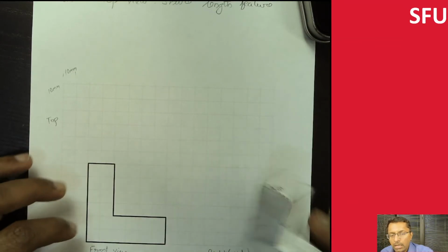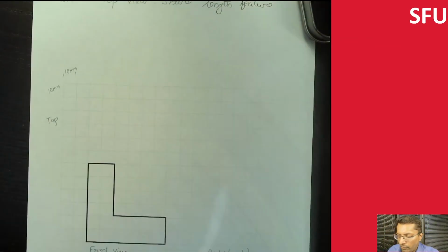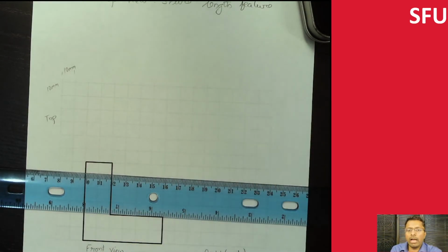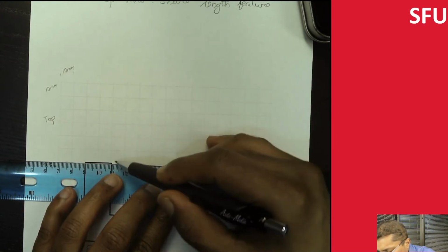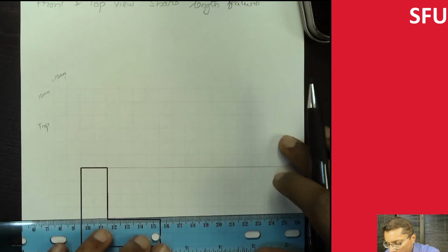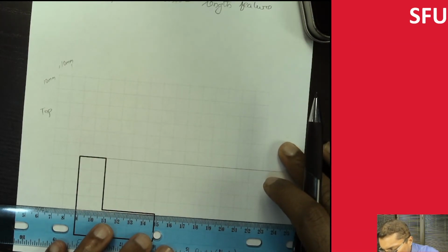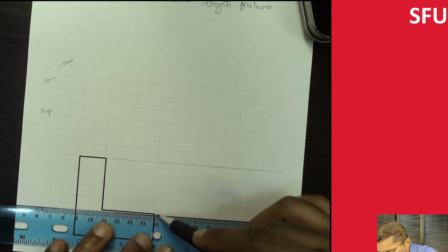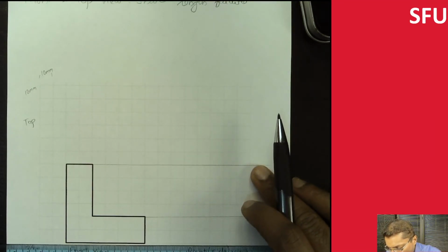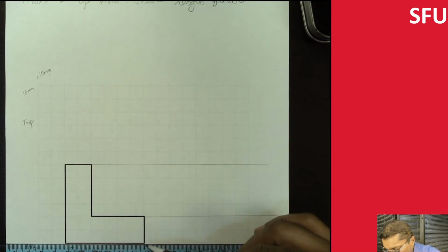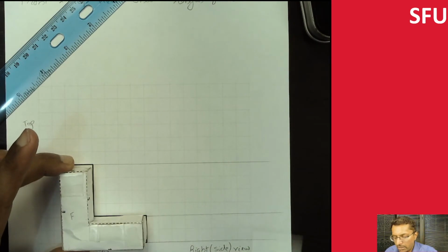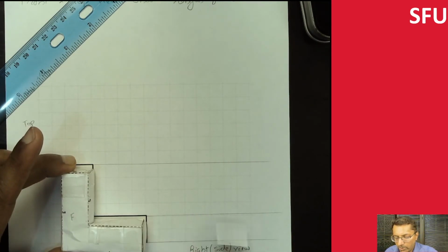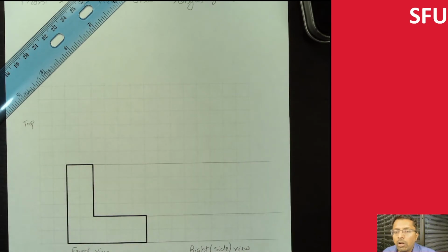And then I'm going to draw the right side view over here. So for that, I would use the construction line. Here I already have my gray lines as a construction line, but nonetheless, it might be useful to do maybe just half a shade darker. I'll pull these lines over here, so hopefully you can see them. So again, pull this guy all the way to infinity and beyond. And then we do the same thing with the bottom edge over here as well. Right, so essentially what I'm doing is I'm saying, hey, these are features, and then based on where I'm going to be drawing the right view, this could go all the way. After I create the drawing, I might want to erase some of it in case I need space.